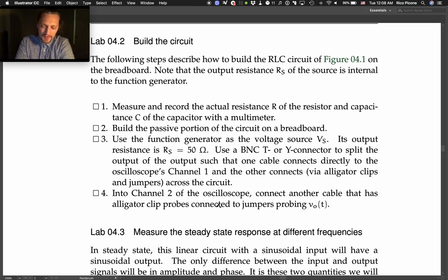I thought about having you guys do it, but I decided to let you just use the nominal value. Recognize that there's error involved in that, and it's probably going to be a major source of error because those inductor values are pretty nominal. They might be 10-20% off easily. So your theory and your experiment might not match perfectly, but it should be pretty good.